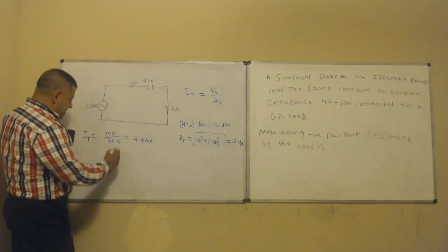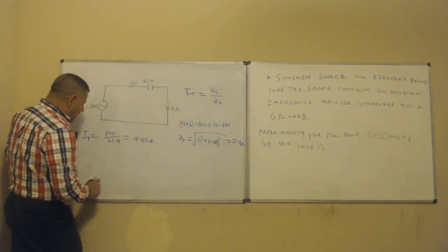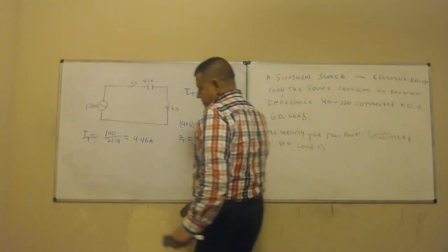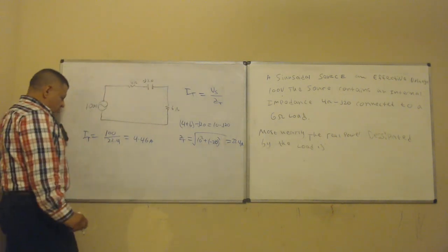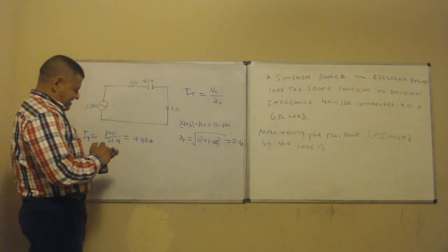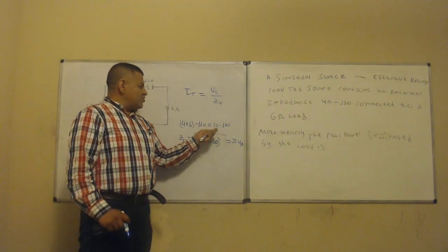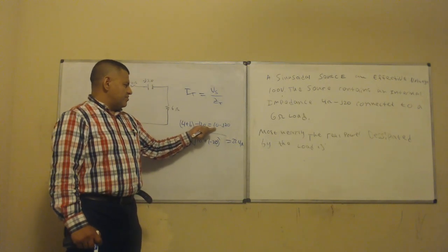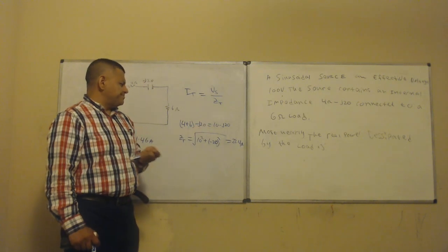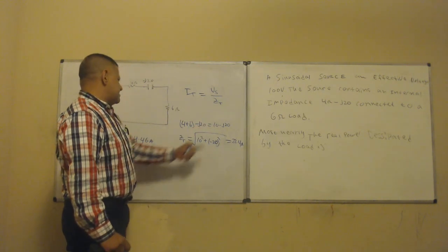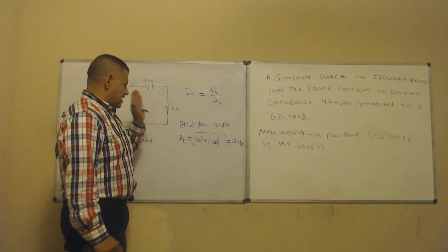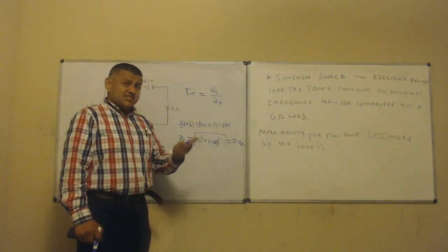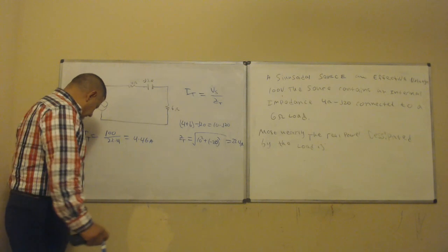So what we can do is say the power, they're asking for the real power. You can complicate yourself in this. You can find the angle and use the power factor, and then use the formula P = 1/2 times IRMS times VRMS times the cosine of the angle, but that gets too complicated. We don't want to complicate things too much.